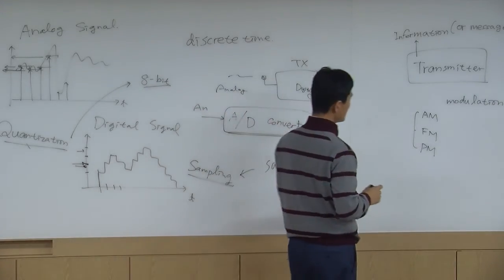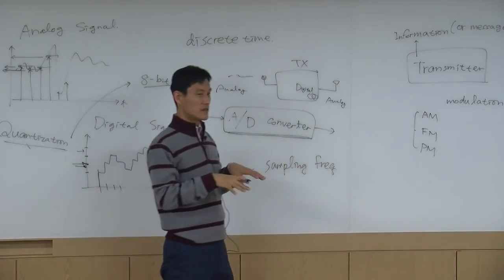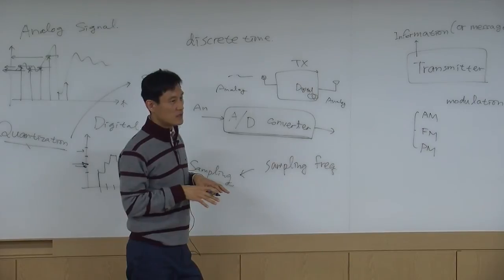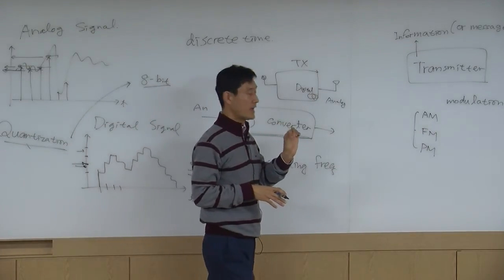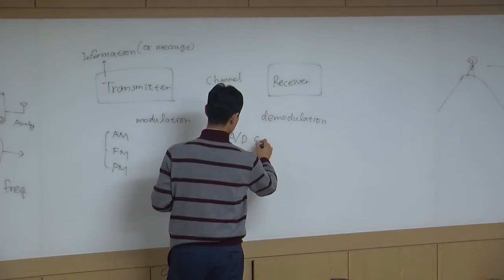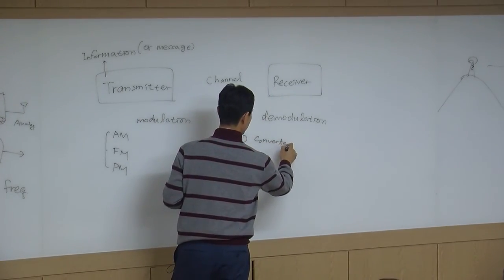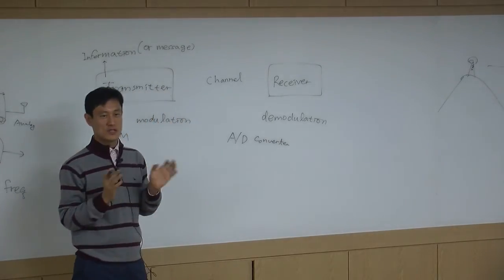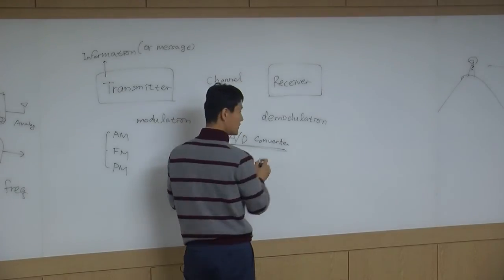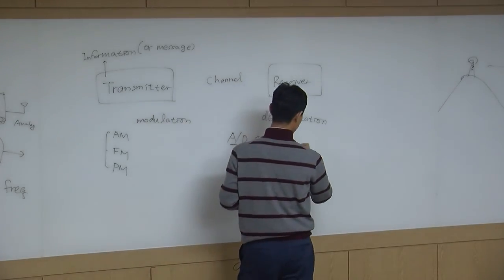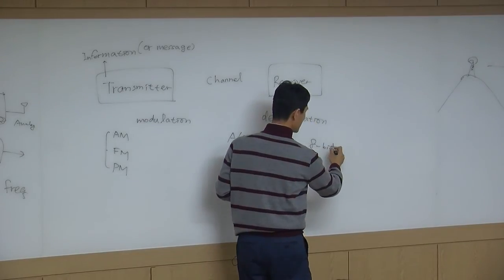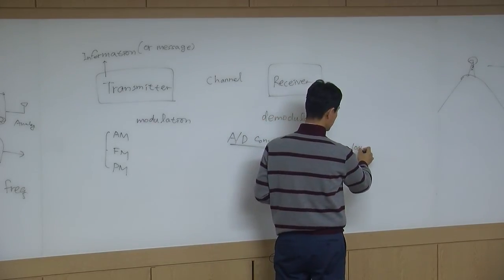So if you Google it, search online for an A to D converter, you can see an actual chip. Every chip has a data sheet with a specification. And that specification for an A to D converter will always say something like, this A to D converter chip is 8-bit with a sampling frequency up to 100 megahertz.